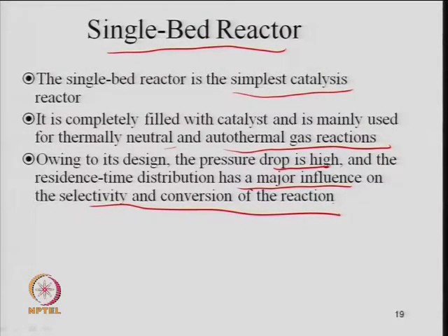So, maldistribution is to be avoided, or distributors are to be designed. So, these things should be looked into, right? That is why the fixed bed reactor or single bed reactor may not be very good when the reaction is highly exothermic or when the catalyst is in powdered form.